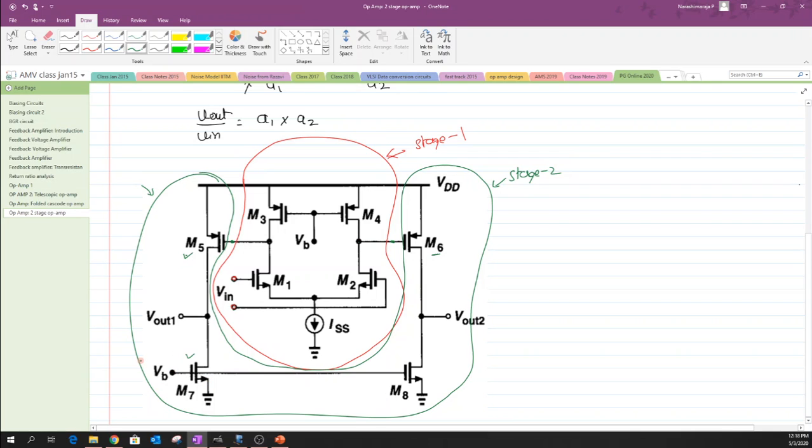So right now let us try to evaluate its gain as well as the output swing of this particular structure. First let me talk about the gain of the first stage, which is labeled as A1. Since the circuit is symmetric, we can draw a line of symmetry at the center, bring this node Vp to the ground, apply the differential input only to the M1 and M3 structure, and then calculate the gain.